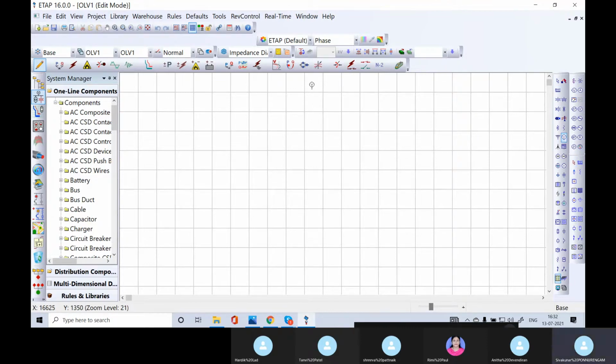This is one single generating unit. Next, this is the 11 kV power generation. The next one is the transformer. So this is the transformer, after the 11 kV generation, stepping up from 11 to 110 kV for power transmission purposes.